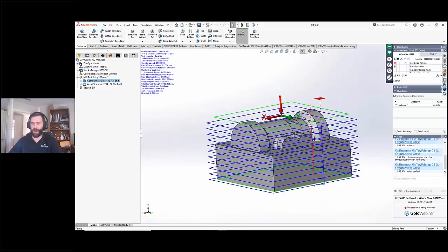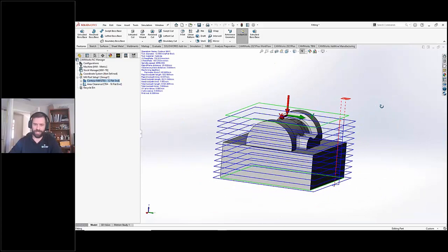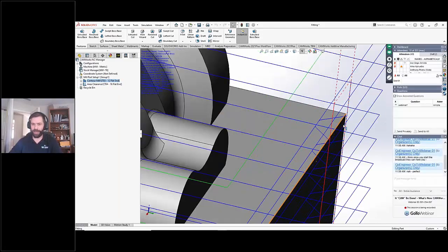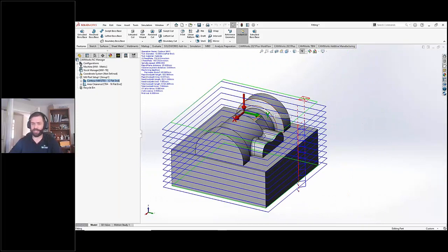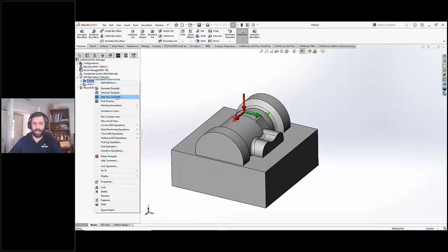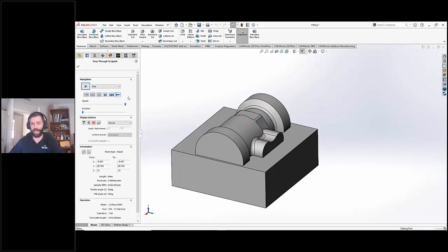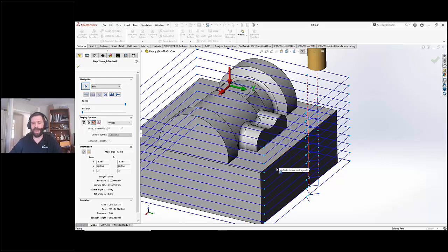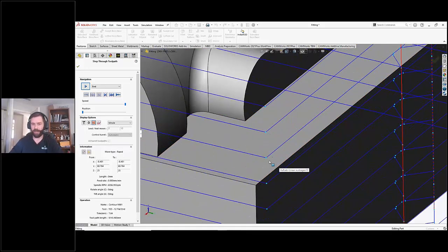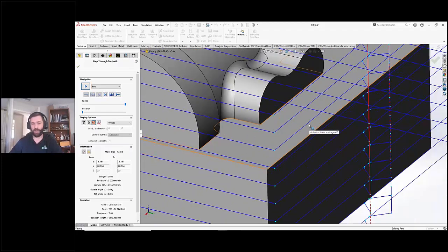But you'll notice when I go to the contour mill here, even though I changed lead in, lead out moves, entry methods, I don't see any color differences here because, once again, this only applies to the 3-axis, multi-axis, and volume mill. If I go into my step-through toolpath, that's where I can enable and view my endpoints. Now, turning that on, I have the color option to change those, very clearly identify toolpath endpoint locations.